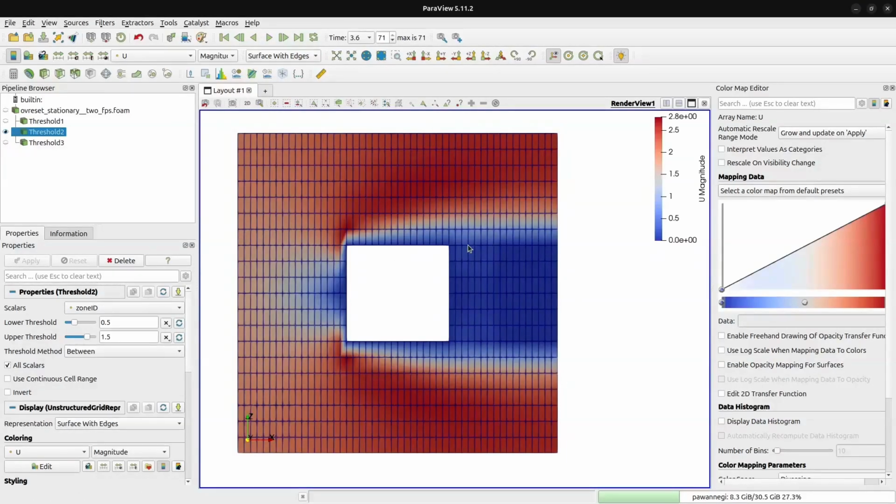You can also create this hole by creating your geometry in such a way. But there is a feature in OpenFOAM which is called topoSet. There you can create topological sets. For example, this is an annular topology, where there is a hole.